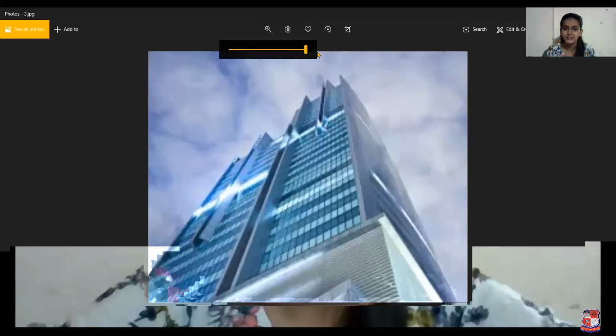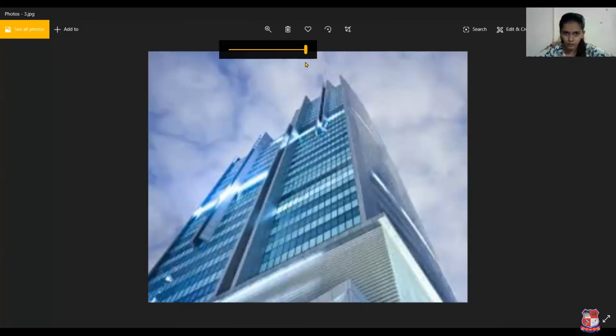You can see here that if we drag a projection from the height or all the corners of the building, it is going to merge in a point. So in 3-point perspective view, the lengthwise projections, widthwise projections and height-wise projections are all going to meet at three different vanishing points. So it's the example for 3-point perspective view.